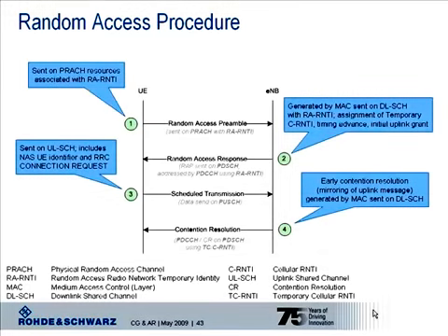The random access procedure contains several steps. First of all, a knock-knock. The random access preamble is sent by the UE, which means: hello network, here I am. The preamble itself is a sort of chosen sequence, which is sent on the physical random access channel.